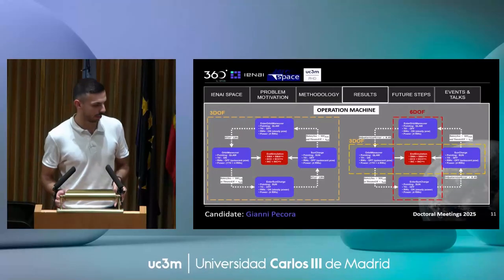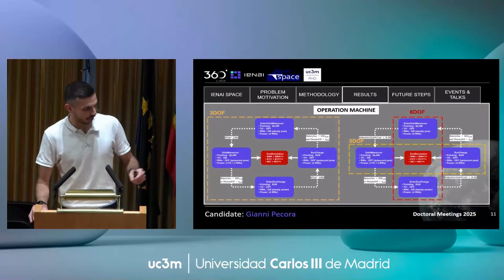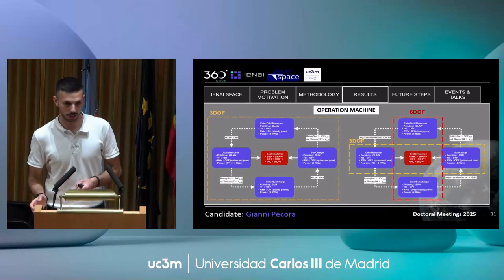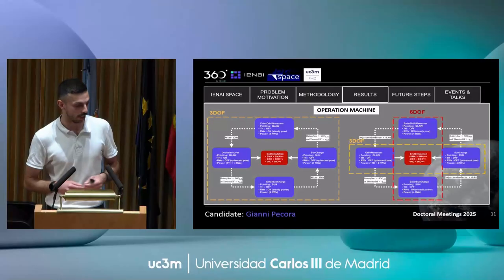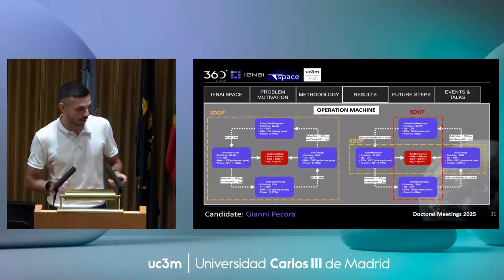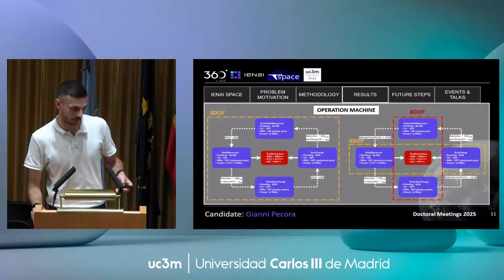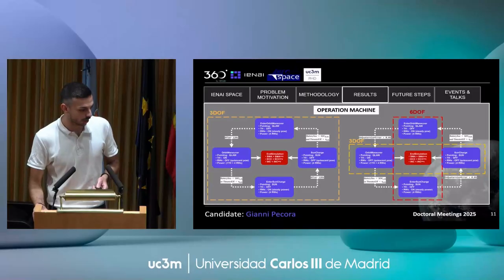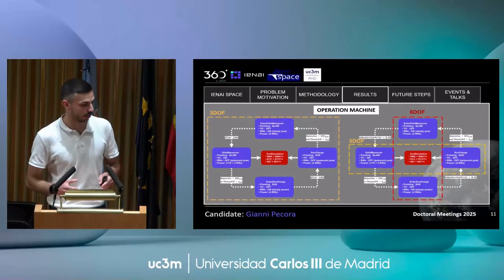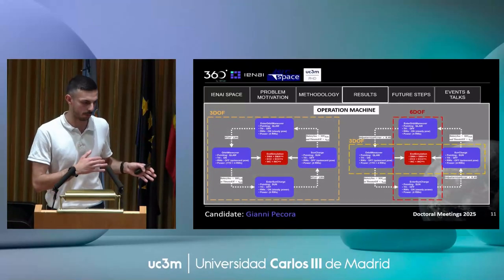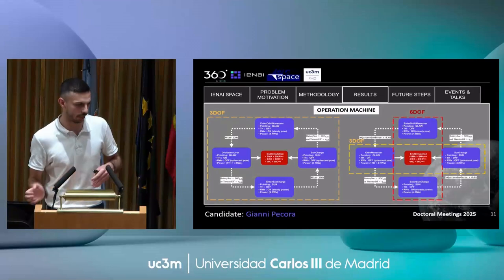I will not go in detail, otherwise I don't have time, but I can say that there are 2 main phases. The one where I'm thrusting and the one where I'm coasting, and I'm pointing with the solar panel to the sun. And I'm switching between these phases based on the state of charge of the battery and the thrust effectivity. And there are other 2 phases where I'm using 6 degrees of freedom for switching from sun to thrust and vice versa.